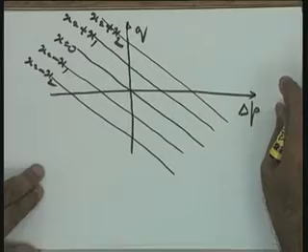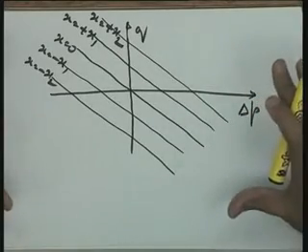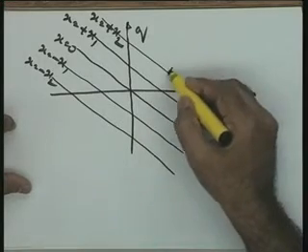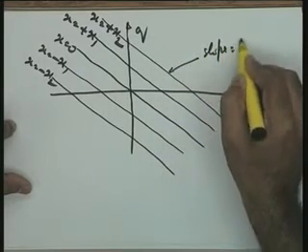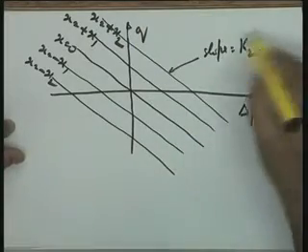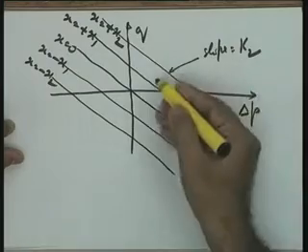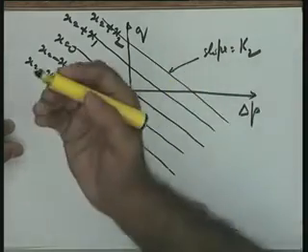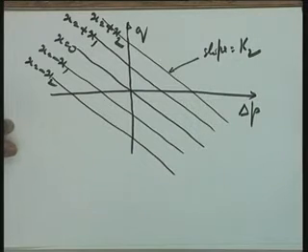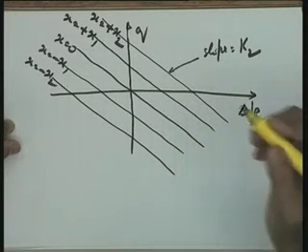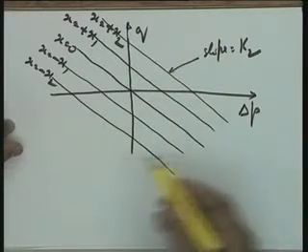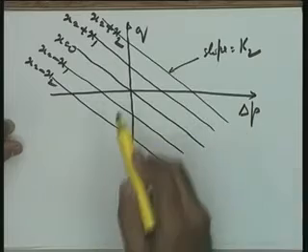Now in this particular case you just see the experimentally obtained characteristic. His question is answered because the slope is negative. This is an experimentally obtained curve. The slope here, as you see, is equal to K2. If I take K2 as a positive value, in that particular case I will have to write this as minus K2. Does it answer your point, please? The numerical value of K2 will be positive. I would have written a plus sign there, but then that df by d del P would have given me a negative numerical value.